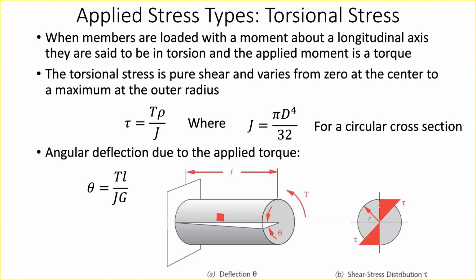So you just take that value, plug it in your equation, specify a torque, specify a radius that the torque is applied at, and then you get a shear stress out of it. So super simple. And again, the derivation is a little involved, but fundamentally, you just need to recognize the behaviors of it, right? So the overall angular deflection is also dependent on this torsional load. So similar to the normal load case, the deflection is just proportional to the amount of load that you apply, right? It's just a slightly different way of computing, I guess, what kind of load it is and what plane the load is acting in.